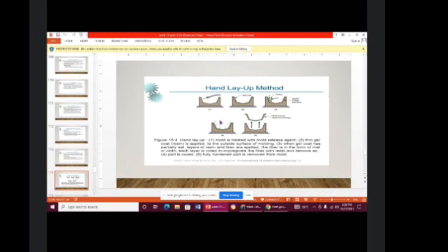Number one, the mold is treated with the mold release agent. So this is the picture. The next is the thin gel coat, which is resin applied to the outside surface of the molding. So this is the coat.